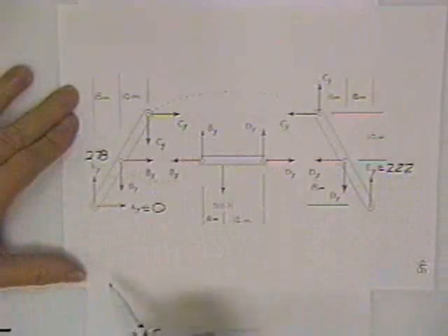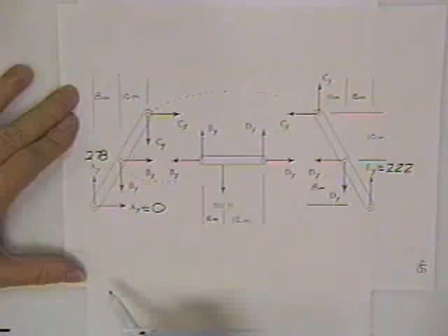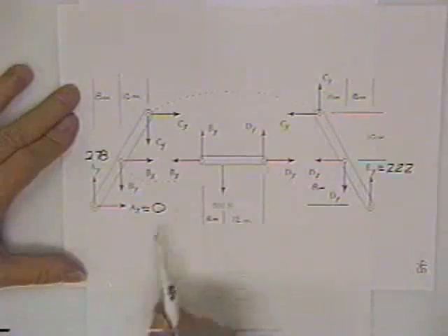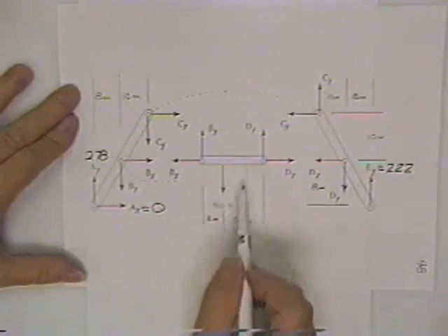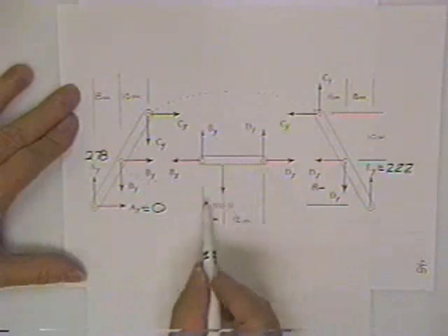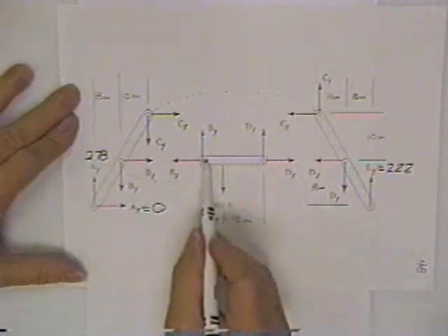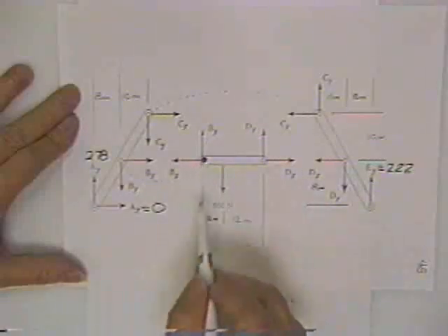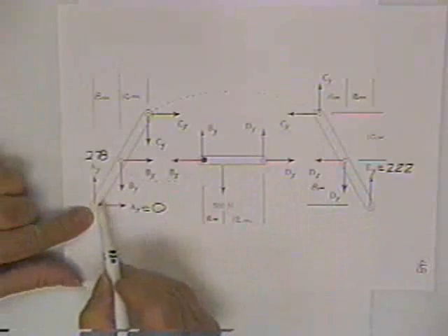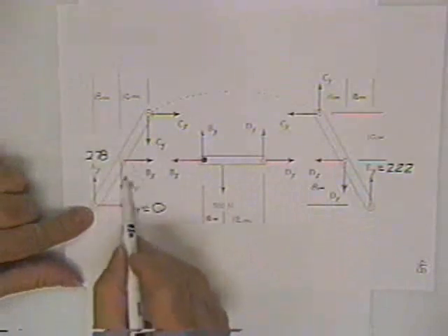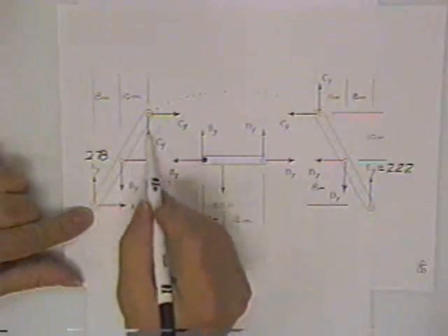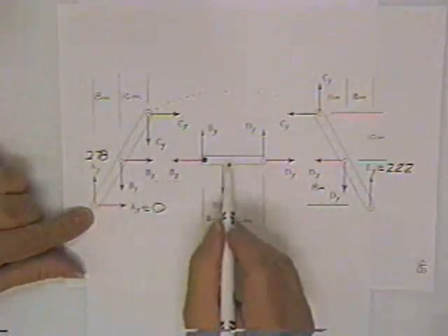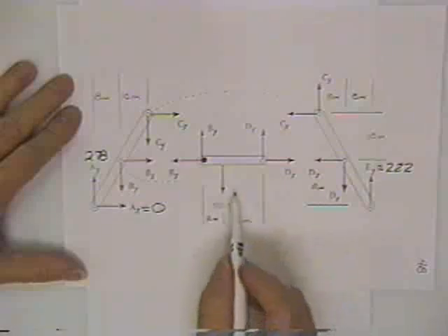Now, these can be put in equilibrium by statics. But your sum of moments equation is always the most powerful equation you've got. If you ever see a horizontal or a vertical member, go towards that first. Because on a horizontal member, a lot of unknowns pass through one point. This one and this one, and this one too. Whereas on this slanted member, if you sum moments about this point, trying to get rid of these two unknowns, these two still have moment arms. So go towards a horizontal or a vertical member first.